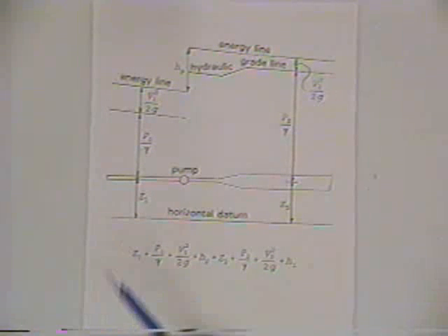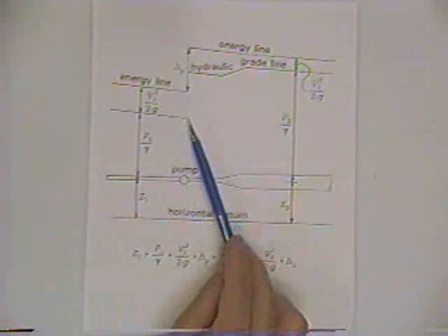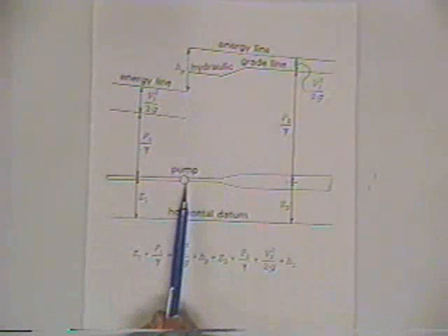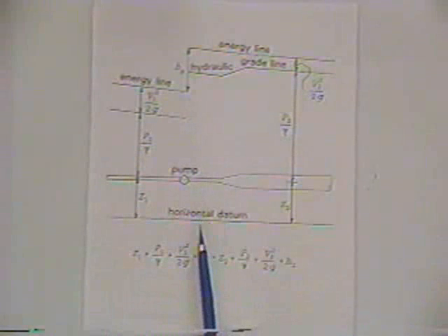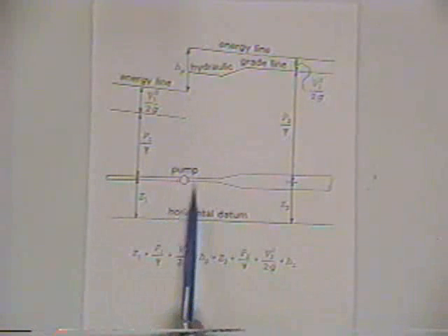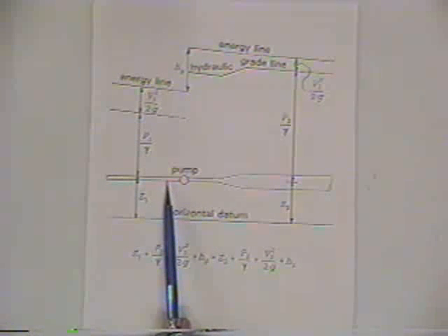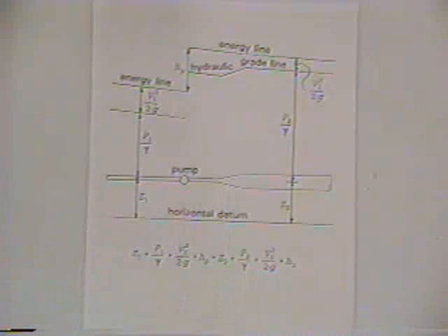And so the pump does nothing to the velocity. You know, intuitively, solving a problem, you might erroneously think in terms of the pump adding velocity, but it can't add velocity. The discharge is the same. Conservation of mass, flow in is equal to flow out. The only way you're going to change the velocity is to change the diameter of the pressure conduit.